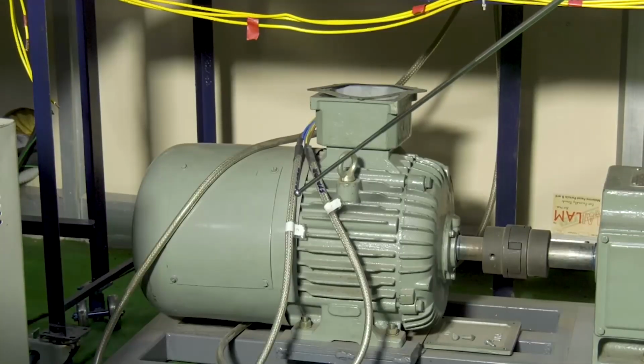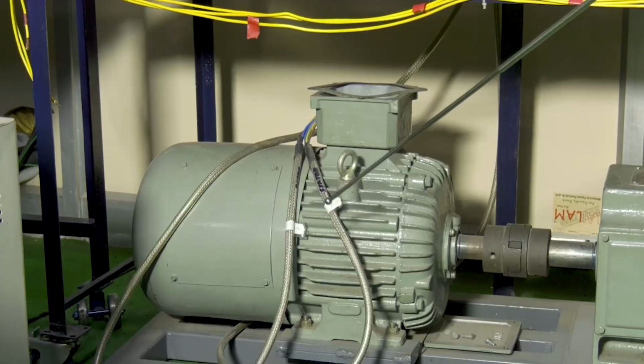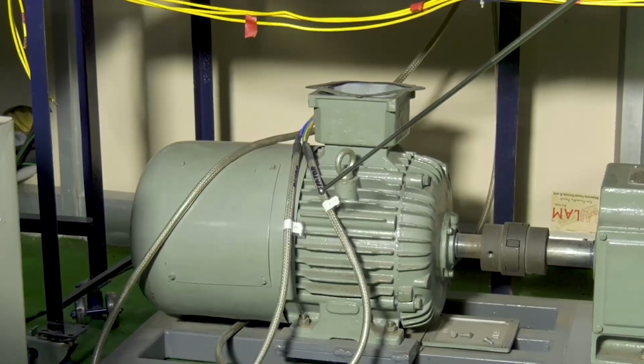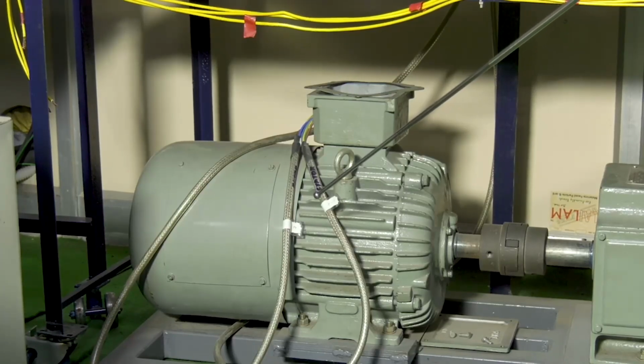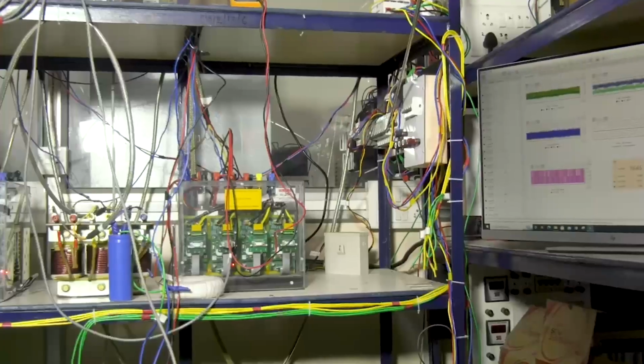This DC motor of rating 2.5 kilowatt, 220 volt, 10 ampere, which behaves similar to a prime mover, is controlled by chopper control, providing different wind characteristics. For obtaining the wind emulator, the wind characteristics along with the wind turbine action is mimicked with the help of a buck converter.